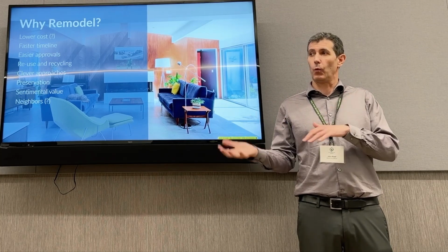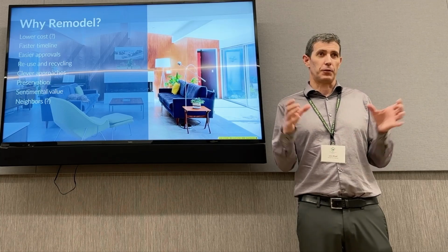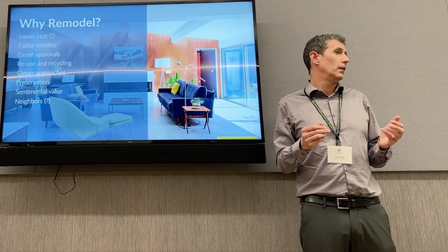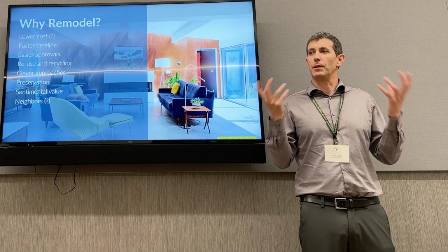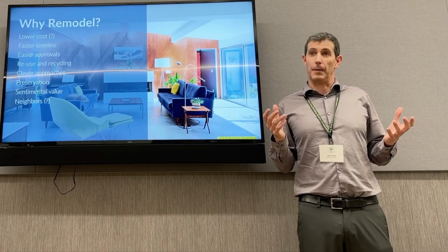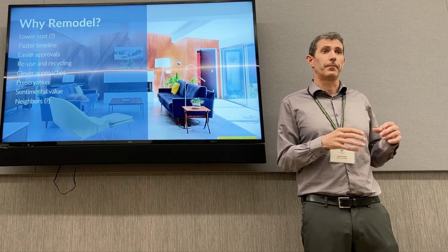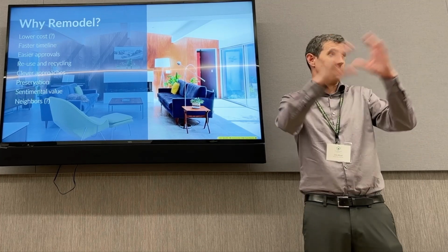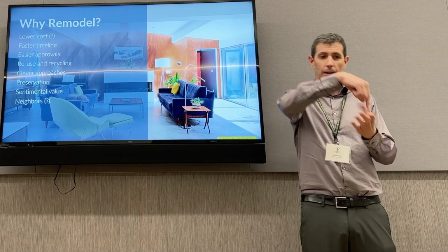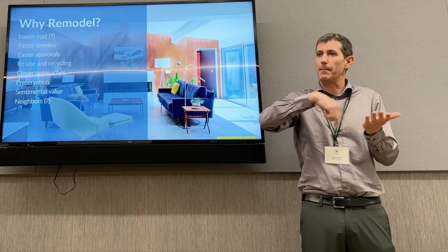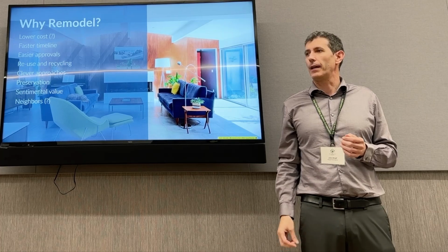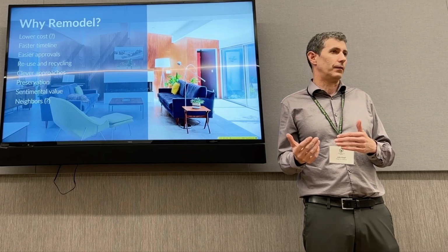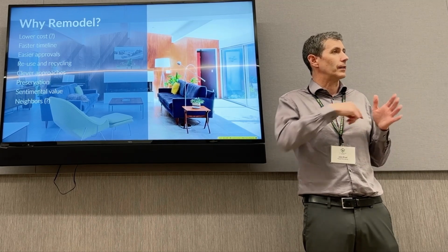We can try to take some of the worst spaces, the small rooms, the low ceiling areas, and instead of assigning those to your living space or your entertainment space or your public space, maybe they used to be those things. Well, now they're going to become closets, bathrooms, bedrooms, and we'll make an addition to the home that contains a new living space, let's say. By doing that, we leave all the walls in place, all the framing in place as much as we possibly can, right? So that's an approach that we take to remodeling that saves a lot of material, saves a lot of energy for the environment, and also saves cost, because we're trying to leave in place as much as we possibly can.